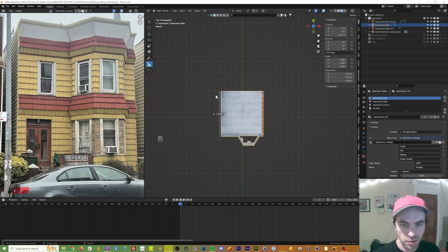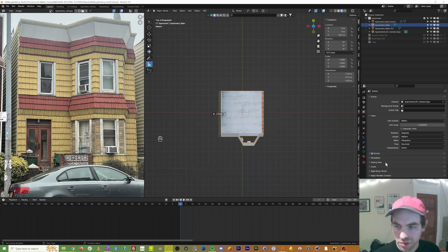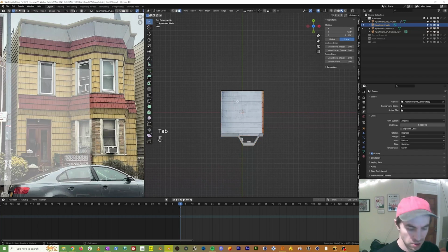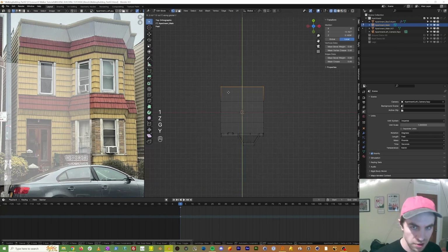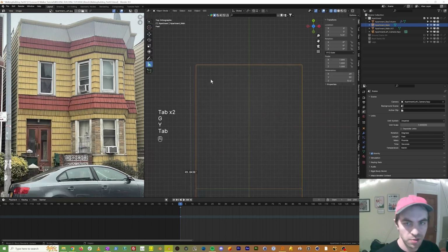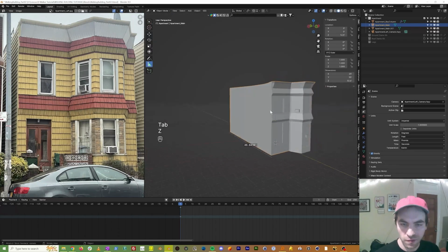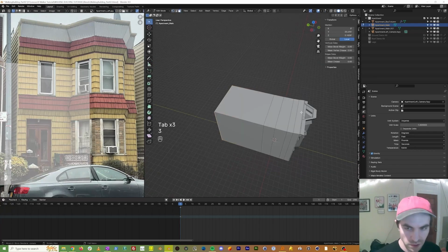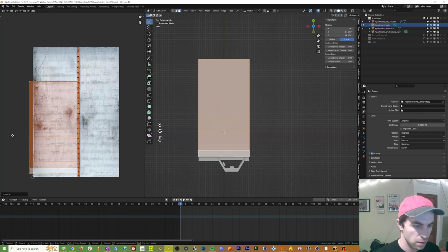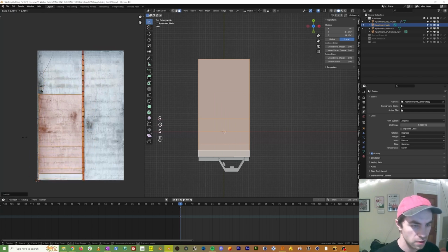So I don't know here. Let's go back to mid-imperial. We're only at 27 feet right now, so let's bring it to 50. From top-down view, we can just do this. And we want it to be approximately there. Those are the dimensions we're looking for. So now let's go back to our rooftop. Let's give that a project from view, and then let's bring that UV so it's right about here.